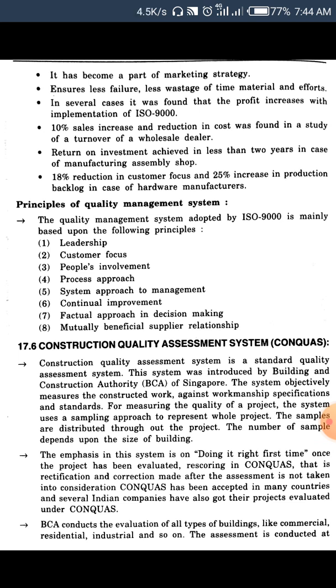This system objectively measures the construction work against workmanship specifications and standards, and for measuring the quality of the project, the system uses a sampling approach to represent the whole project. The samples are distributed throughout the project, and the number of samples depends upon the size of the building.